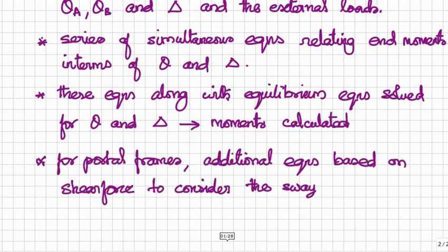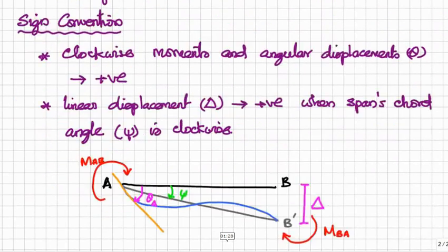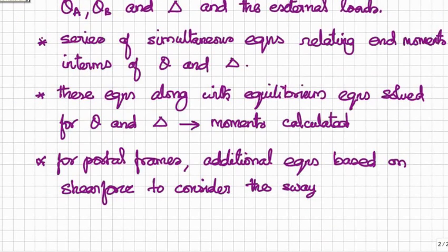For portal frames which are non-symmetric in any aspect, additional equations based on shear force are to be considered to account for the sway of the frame.